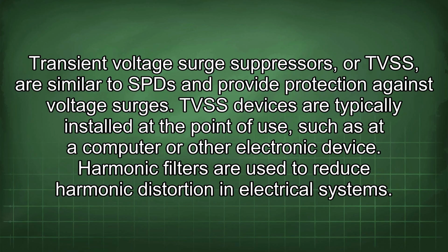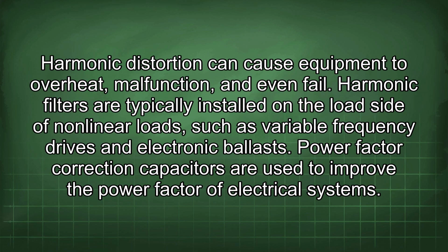Harmonic filters are used to reduce harmonic distortion in electrical systems. Harmonic distortion can cause equipment to overheat, malfunction, and even fail. Harmonic filters are typically installed on the load side of nonlinear loads, such as variable frequency drives and electronic ballasts.